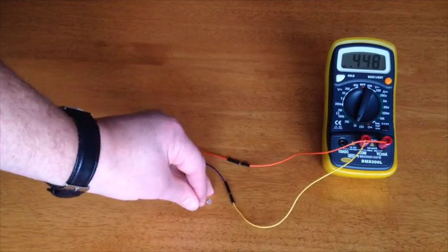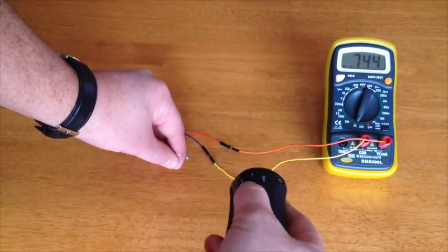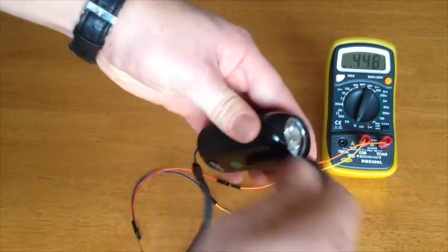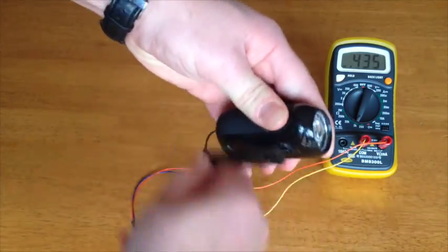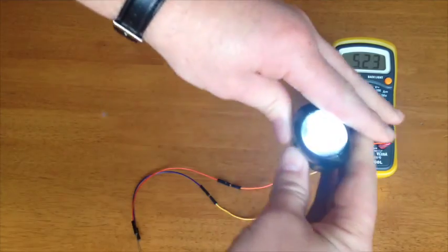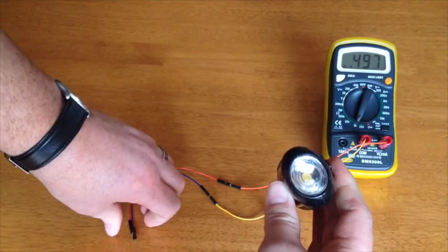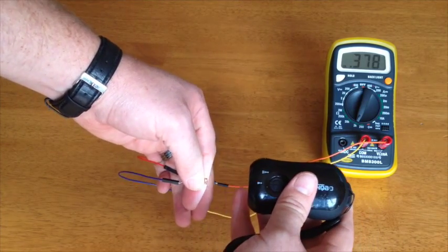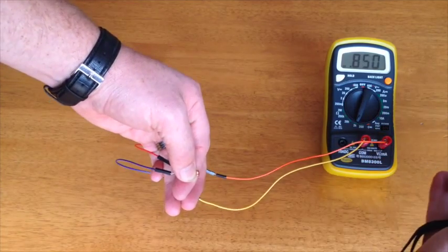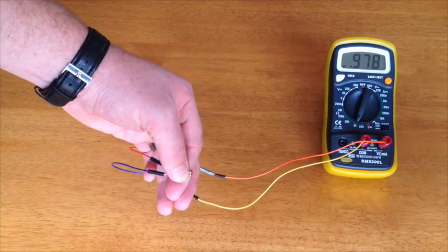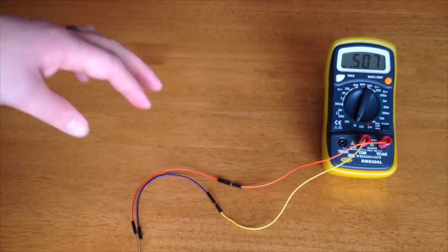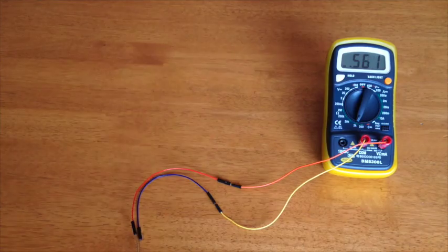Now, one of the possible experiments you can do is take a flashlight or a torch here, and you can shine, oh sorry, this is a wind-up flashlight, so you can see that that's giving off light. Okay, so you could look at how resistance is affected with the distance of light, and you can see that the resistance is increasing as the distance between the light and the LDR also increases. So that's one possible investigation you could do.